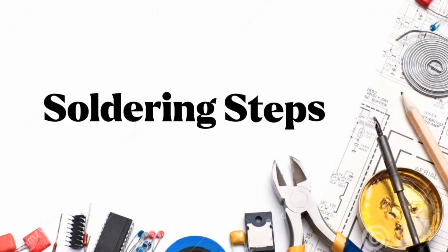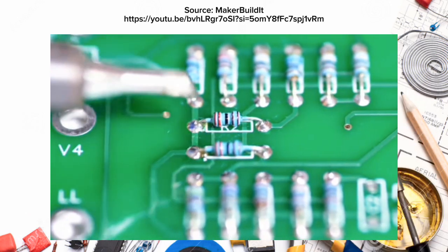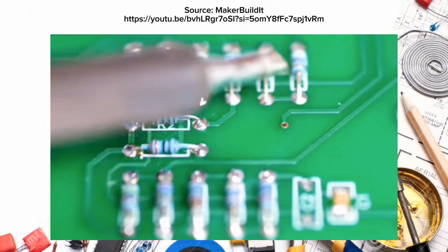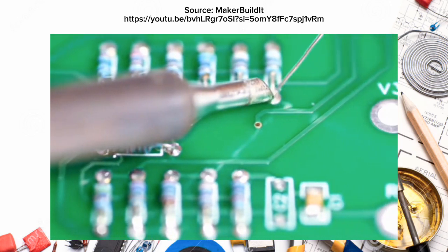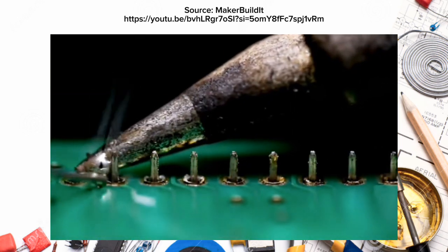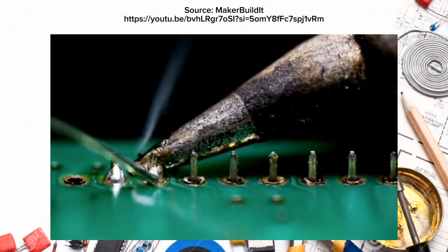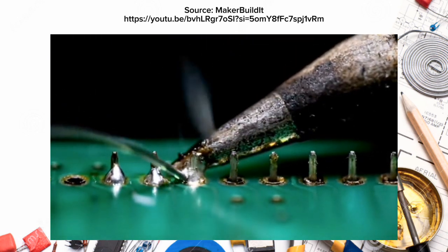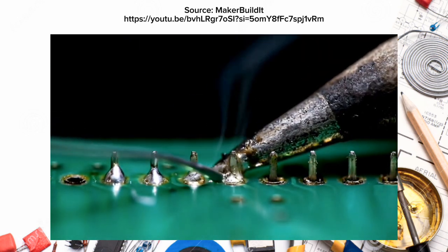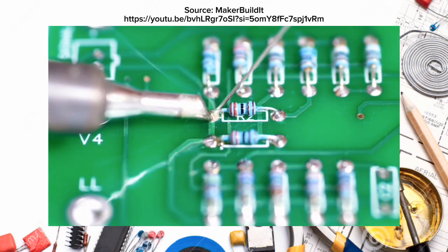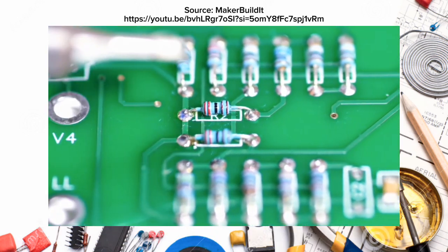Soldering steps. First, here's how to solder. Heat the joint with a soldering iron. Second, apply solder wire to the joint, not the iron, so the solder flows evenly. Third, ensure the joint is shiny and conical. Reheat it if it looks dull or blob-like.